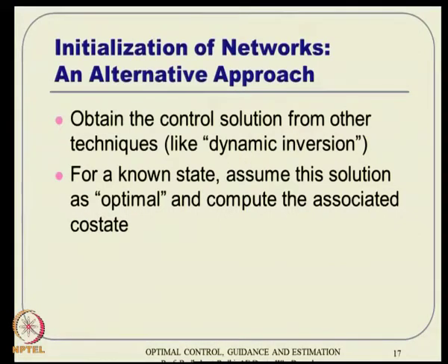So, you will invoke some sort of pseudo inverse, which I personally sometimes do not like. If the dimensional discrepancy is high, say one control and 8-9 states, then obviously this is not a good approach. But if it is of compatible dimension, like 3 states and 3 controls, or probably 3 states and 2 controls, then you can probably use this. The advantage here is that you are not linearizing the problem.